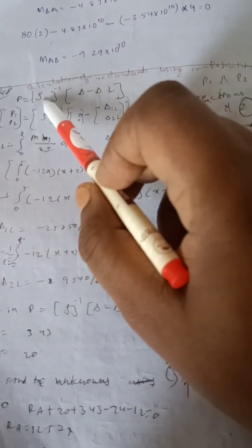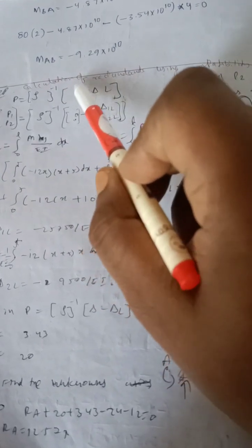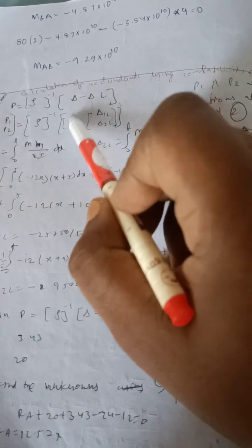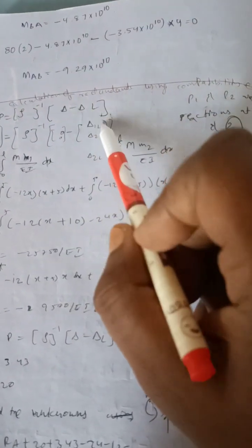It is a flexibility matrix which we have already calculated, F11, F12, F21, F22. This is yielding related. If it is a settlement problem, then you will get these values. If it is without settlement problem, 0, 0 you need to take. Next, delta L is displacement. Now what is this displacement matrix?